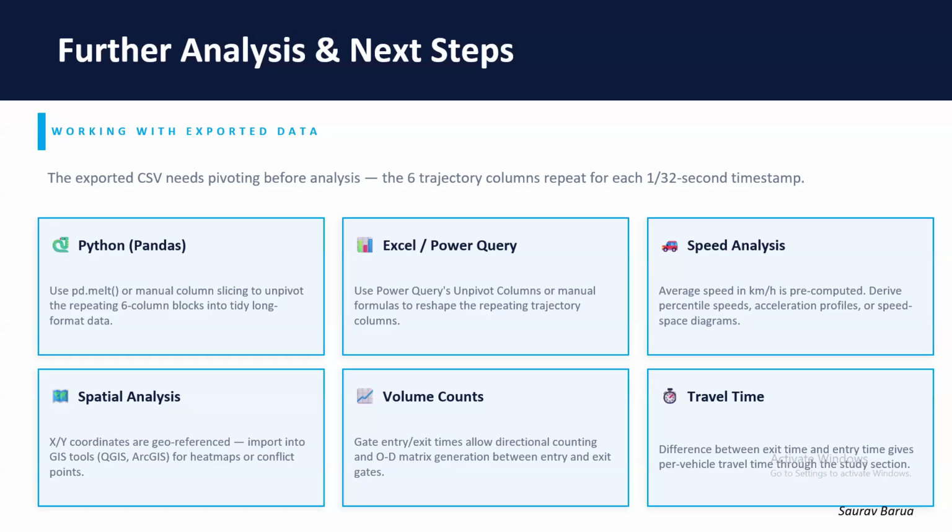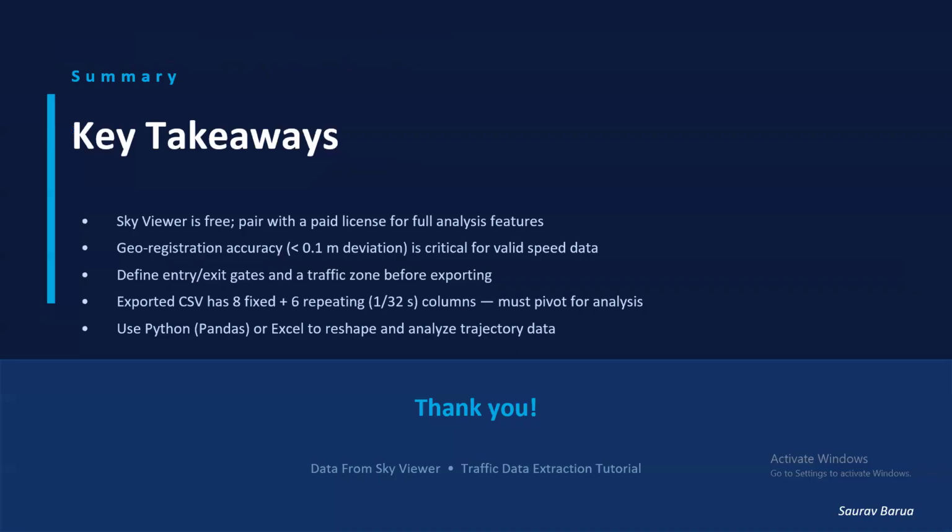We can also calculate volume counts. We have gate entry and exit times and allow directional counts, and OD matrices are generated. We can generate OD matrices between entry and exit gates, and most importantly, we can use the data to calculate the travel time between entry and exit gate for every vehicle within the study area.